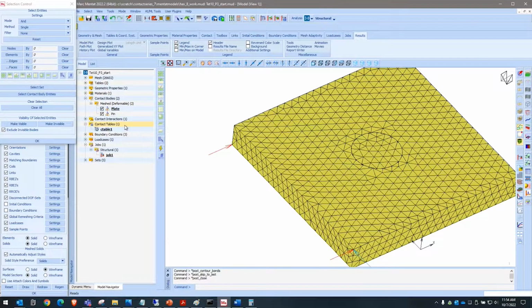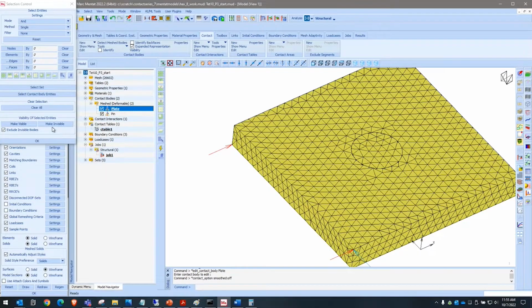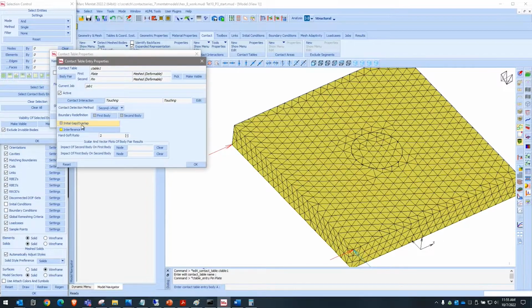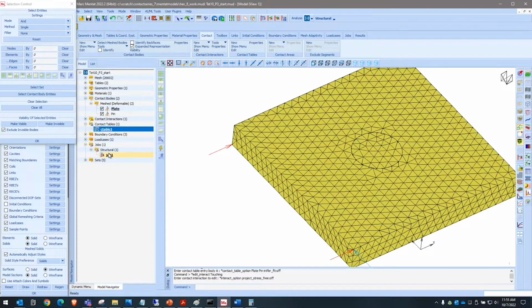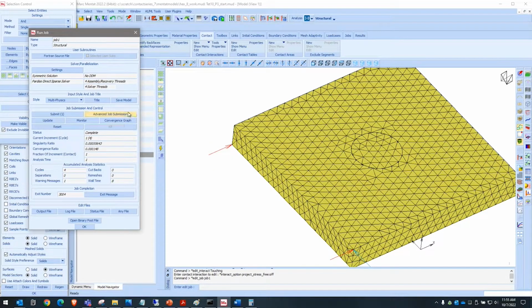Okay, so the last one I'll show you is if I do not smooth the plate for this one. I didn't show it on the other mesh, but it happened the same. I need to switch back off the interference fit in the projection. Sorry, this one rather. The previous mesh, even using these settings, gave okay answers. I think I just need to change the direction.